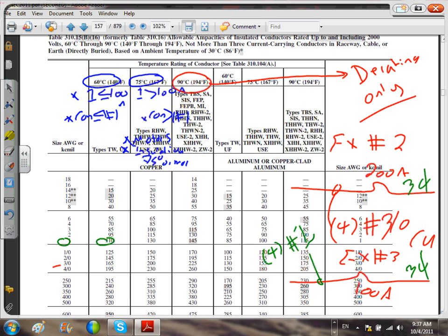The insulation THHN is rated for 600 volt. So on the same conductor, I can pull 480, 600 volt, 277, 120, 240, any voltage. Under 6 or under. Thank you. Yeah, because 6 or under, yeah.